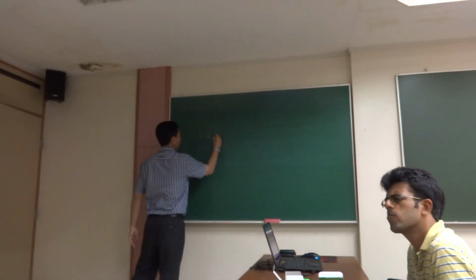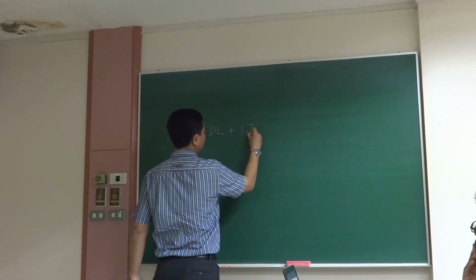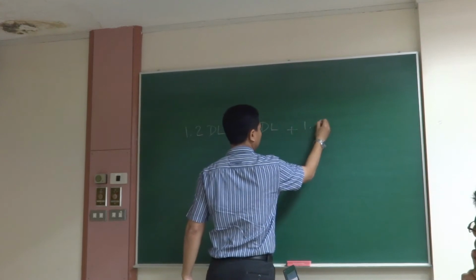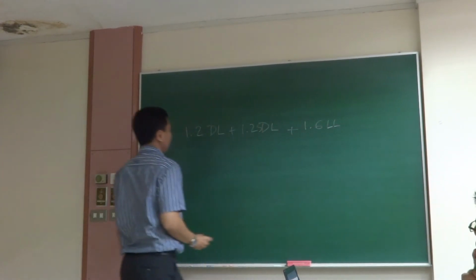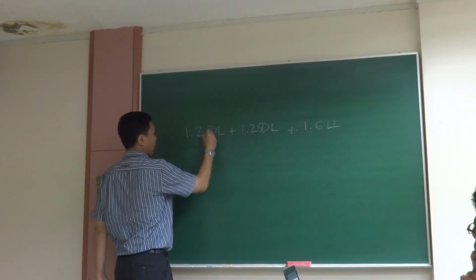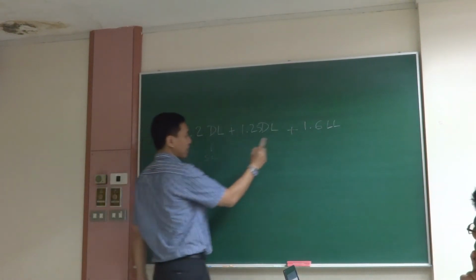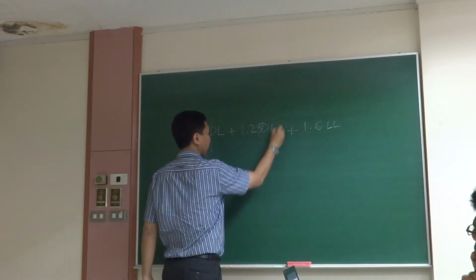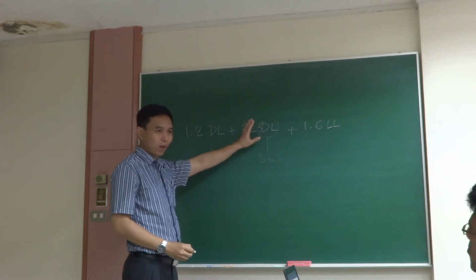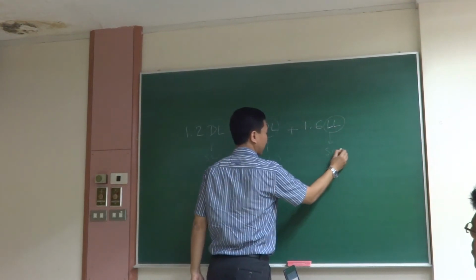Normally our gravity load combination is 1.3 dead load, and STL also considered as dead load, STL plus 1.6. So if you have self-weight multiplier 1 in this load case, it considers self-weight one time. In STL you consider self-weight again, so this one also has self-weight considered, plus the ceiling load and partition load. And for live load also, if you use one, it is also considered self-weight.